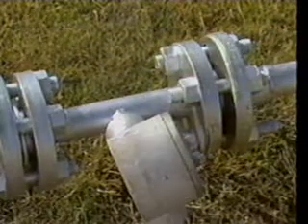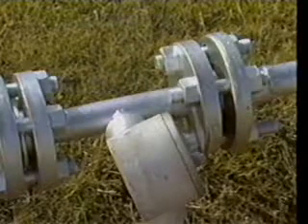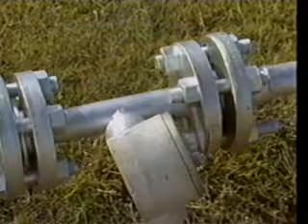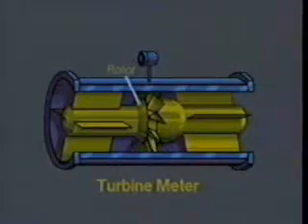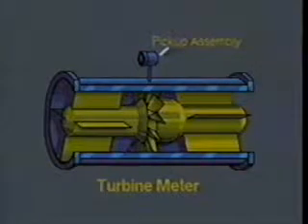Turbine meter construction is relatively simple. The meter itself is installed directly in the meter tube. The meter is a precisely balanced, free-running rotor mounted in a cylindrical housing, similar to a flanged pipe. This unit is mounted on the pipe center line. A magnetic pickup assembly is positioned as close to the rotor as possible but does not penetrate the housing.